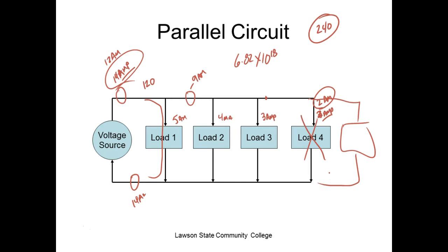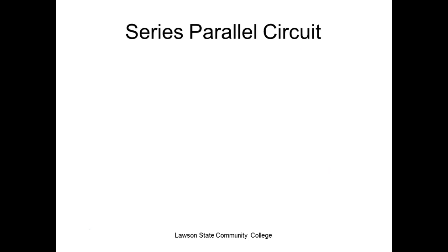So we're going to have plenty of parallel circuits. The two circuits we're going to run in PLCs and in motor controls, we have two circuits available to us. We have a single load, a series circuit, and we have a multiple load parallel circuit. That's the only two available. The only time you'll run into true series circuits, you run into them in Christmas lights, right? You understand that? And in electronics, we use a lot of series circuits. Probably the most popular in electronics is something called series parallel, which we won't even.